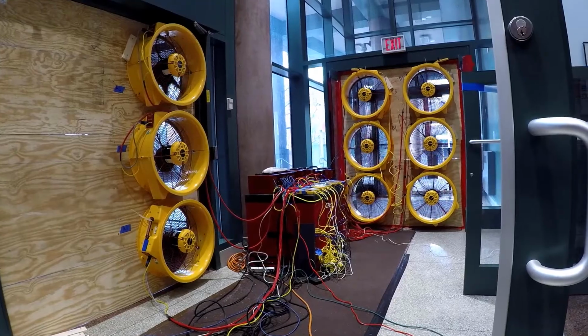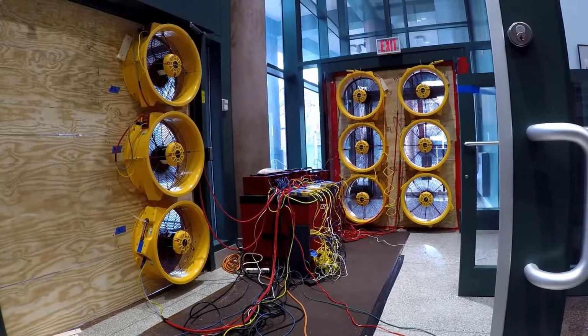Happy Tuesday, everyone. This week we're going to talk about the difference between common control and individual control whenever you're running more than one fan. Common control is the gauge and fan configuration that we're going to use when we're testing a large space. So if we're doing a whole building test, common control is what we're going to use there. That's where we have one gauge telling all of the fans what to do.